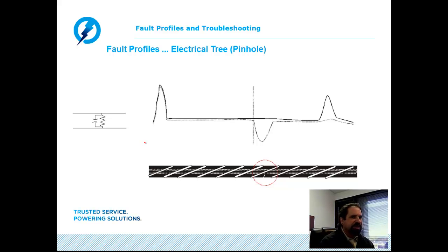So again, we discussed this in the cable fault part 1, but if we were running the arc reflection test, if you remember from the first of this webinar series, the first pattern is the low voltage pattern, and will show us the end of the cable. The second picture that we're going to take is while we are discharging with the surge generator and creating breakdown. We are also sending pulse echo pulses with the intent that when the arc is present, the circuit at that moment of time is a short circuit, and we capture the negative reflection corresponding with the arc that we drive on the cable through the thumping process.